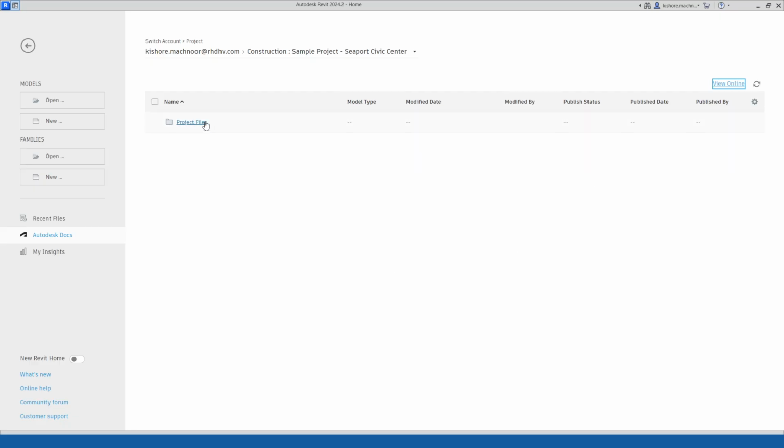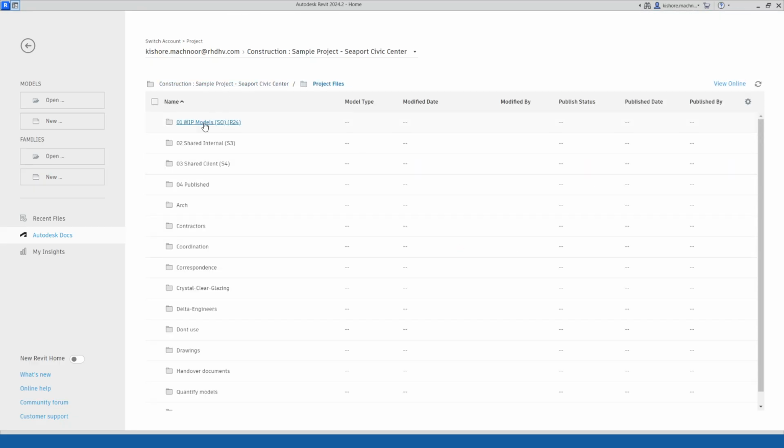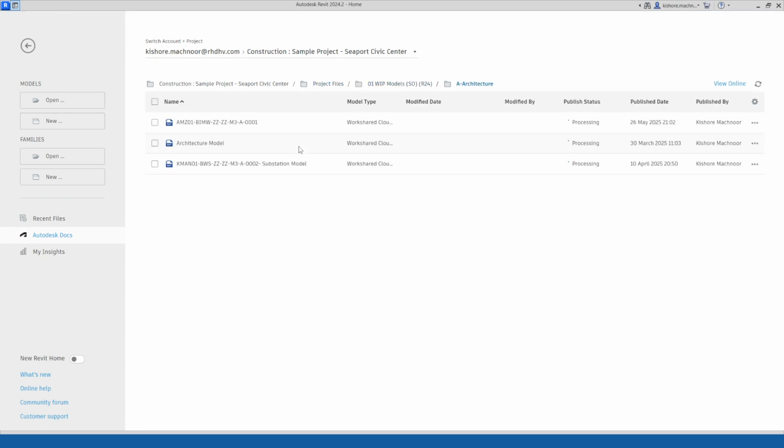You can see the number 2 model. I can't see it from Revit. Can you see that here? No, right? That's because it's a non-workshared Revit project or model. Only the Revit models which are enabled for work sharing can be visible in this Revit environment. A non-workshared Revit model should be opened via Autodesk Desktop Connector. I'll come back to that topic in coming sessions.